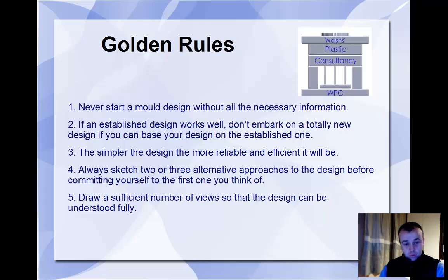Simple designs work best. They're more efficient, reliable, effective. Don't unnecessarily overcomplicate the mold design. It's complicated enough as it is, so try and make it as simple as possible.